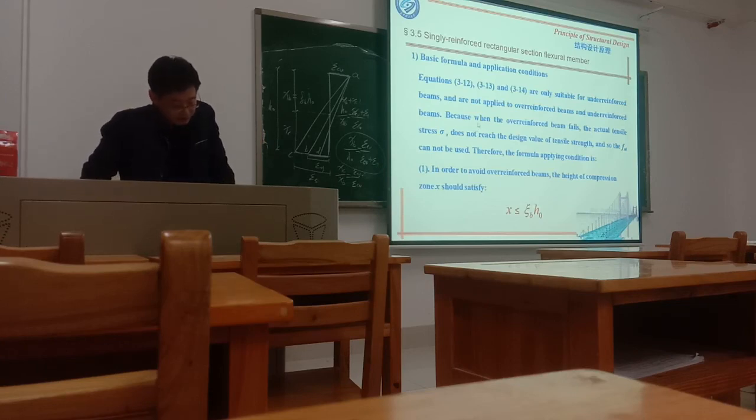Because when the over-reinforced beam fails, the actual tensile stress doesn't reach the design value of the tensile strength, so fsd cannot be used.